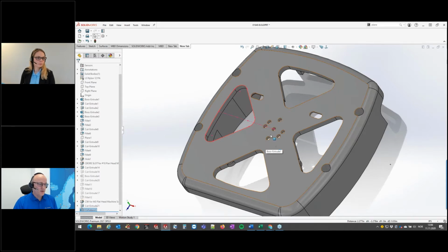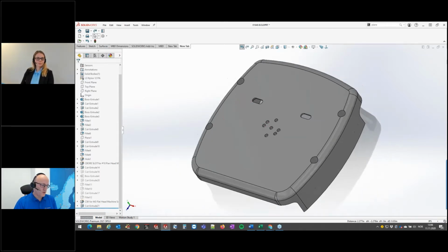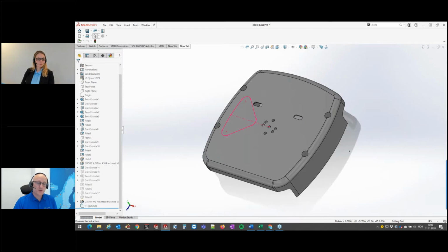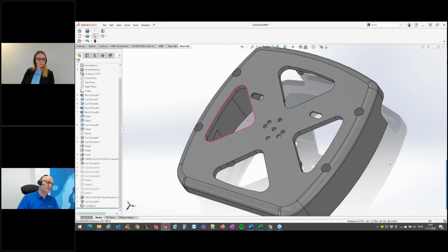If I want to change what I've done, of course, I can press undo. I can undo my way back to the cut and also to before the cut. And new in 2021 is that you can also use redo on a feature level. So if I now press redo, I can go back again. Earlier, if I did undo too many times, I had to recreate the later steps if I wanted to undo my undo, so to speak. So redo is now available on feature level. Very good new thing in 2021.